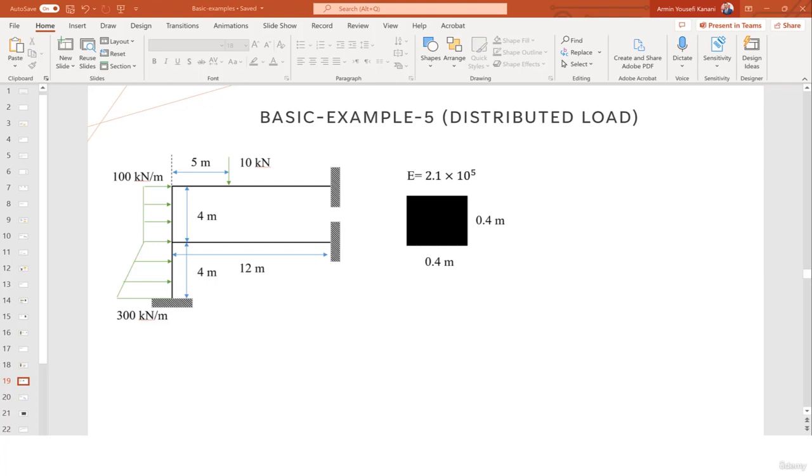Hello everyone, in this tutorial you're going to learn how to simulate a 2D wire bracket in Abaqus. This example is going to be simple, however there are some new elements that you're going to learn for the first time. For instance, how to apply a distributed load, or how to use a field function to generate the equation to apply a triangle distributed load. And also you're going to learn how to partition the line to apply a concentrated load at a specific area.